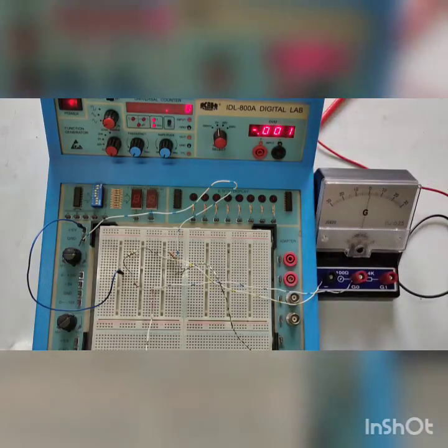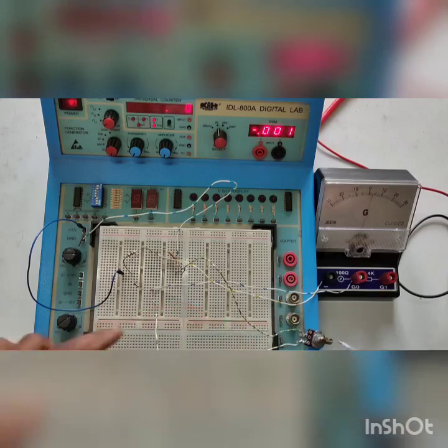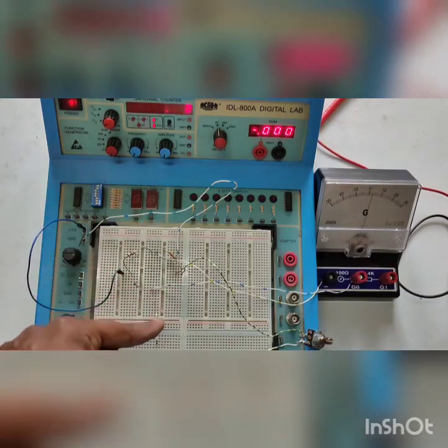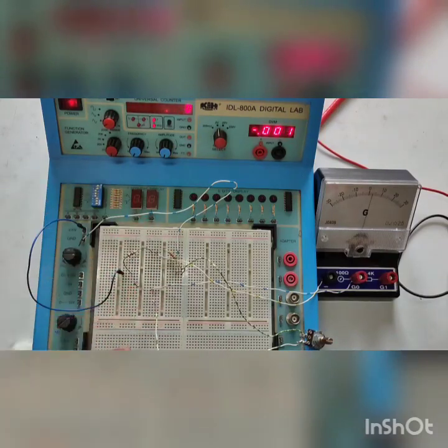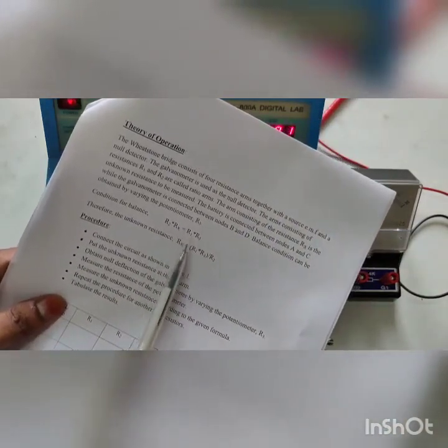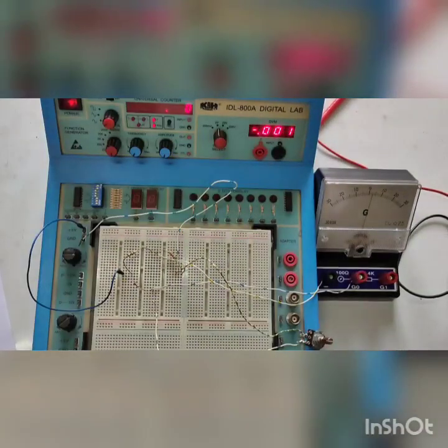Now we have to measure the resistance value of this potentiometer, and we already know R1, R2, and this one is R3, the potentiometer. If we can measure the resistance of this potentiometer, then we get these three resistances, and this one is the unknown. So by using this formula, or this formula, both are the same thing, we can calculate the Rx.